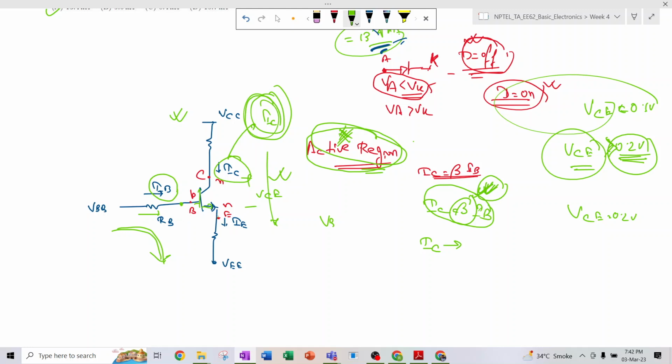Yeah. So suppose there is no resistor and this terminal is grounded, so VB is 0.7 volt. You should always have more than 0.7 volt appear over here, and only then will this PN junction operate and the current conduct. But if no current is flowing through it, there is no current conduction in this region. That means the transistor is in the off state, in the cutoff region, where no current is conducting, right? You got it, right?